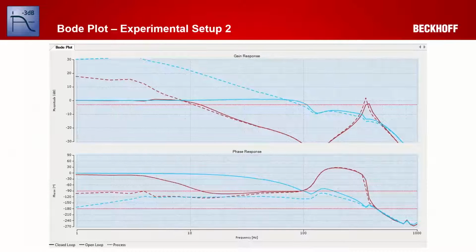Here in the comparison in the Bode diagram, the brown curve shows the anti-resonance and the resonance. And after our tuning, the blue curve is without resonance and with a higher bandwidth, approximately 100 Hertz. So this was a second example, or in total we checked with 2 examples how you can optimize an axis, analyze an axis with the help of the Bode Plot tool, and you can have a massive improvement.